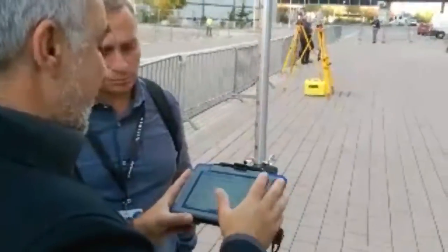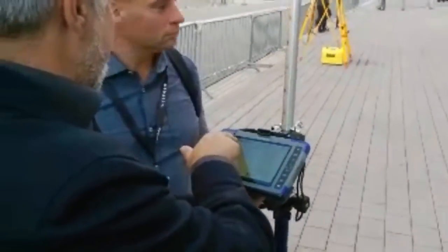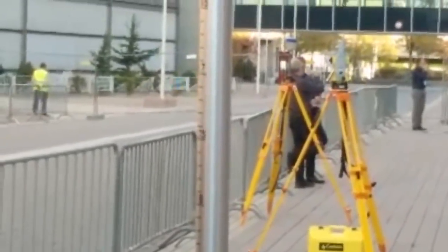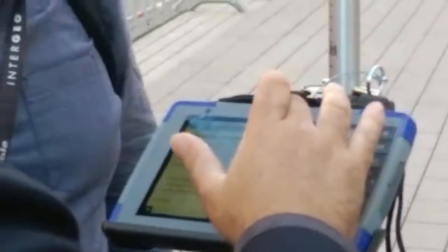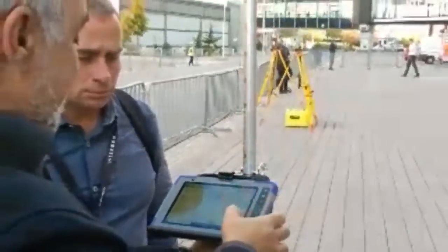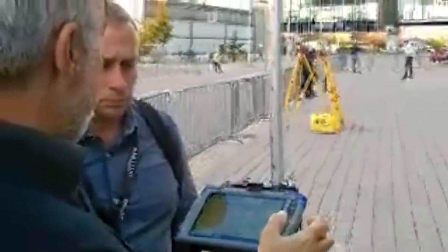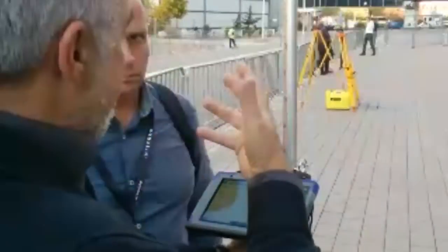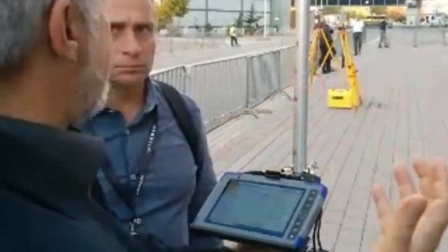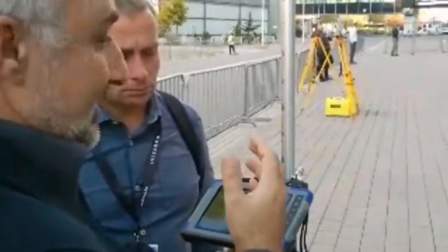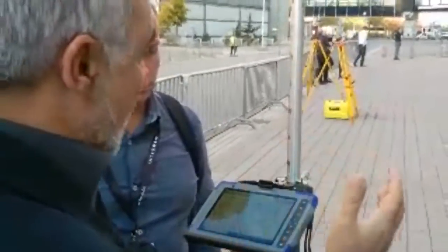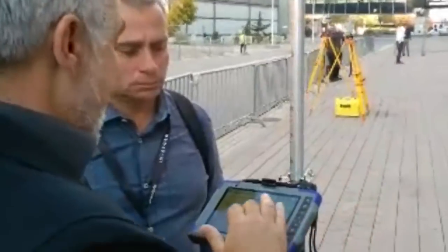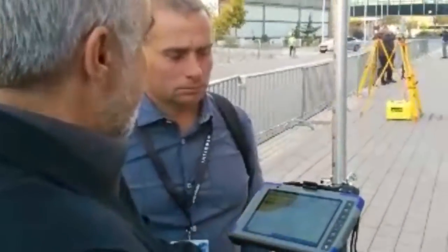Well, what we see here is I still got a yellow color in the total station. That means I didn't lock. So first I will do a global search somehow, or whichever search. If I don't have a global search, I could use robotic and joystick or whatever one time. After we align the GPS, we can use the GPS for searching. We don't need any more power search or remote control, which is very expensive in a robotic. So at this time, I will do this.